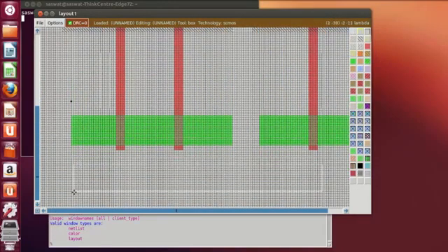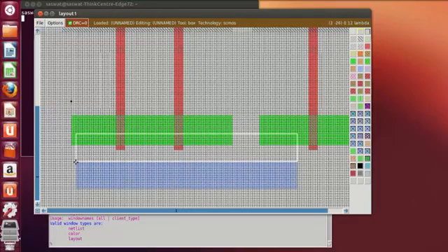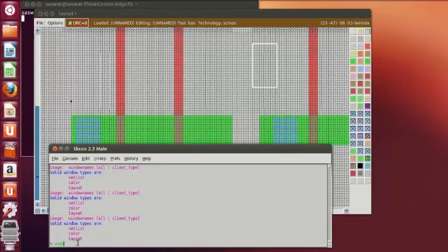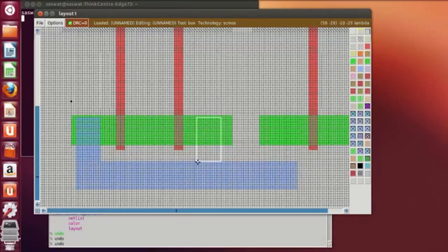Now the sources of the two NMOS, they are also connected to ground. So select the area, then from here to here, then middle click on M1, from here to here, M1, then again M1. Undo. This should be connected over here. Then middle click on M1. Now you can remove this part, middle click outside. Okay, so these two sources are grounded.